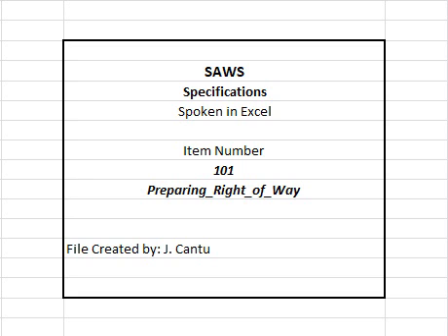9. Material to be removed will be designated as salvageable or non-salvageable in the contract documents prior to bidding by the contractor. All salvageable material will remain the property of SAWS and will be stored at the site as directed by the SAWS inspector. All non-salvageable materials and debris removed shall become the property of the contractor and shall be removed from the site and disposed of properly. 10. All asphaltic material shall be disposed of or recycled at a facility authorized to accept the asphalt for such purposes and applicable to appropriate guidelines and regulations.